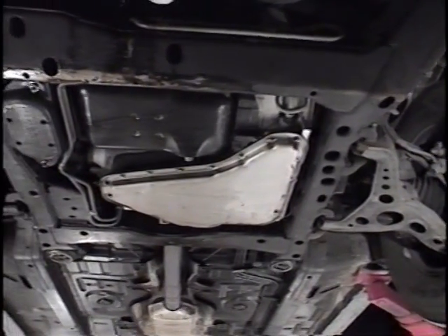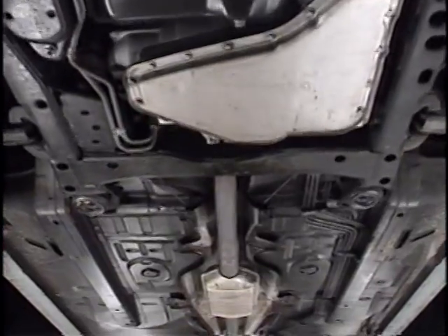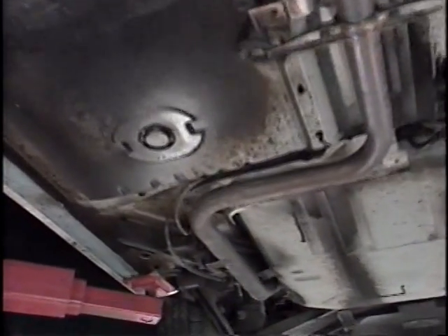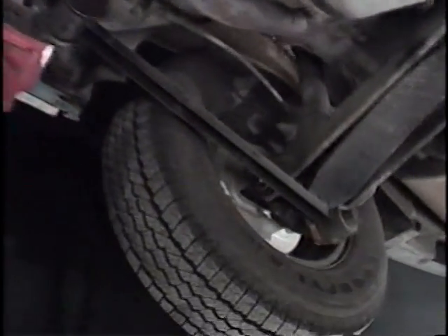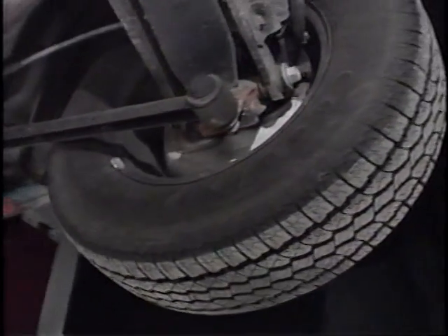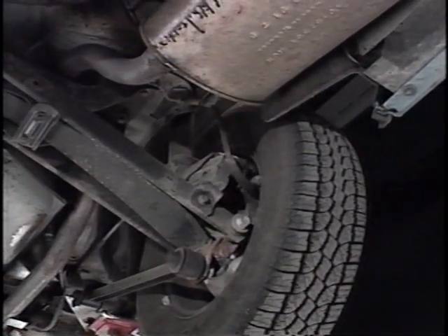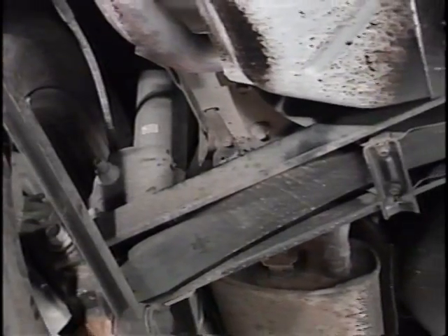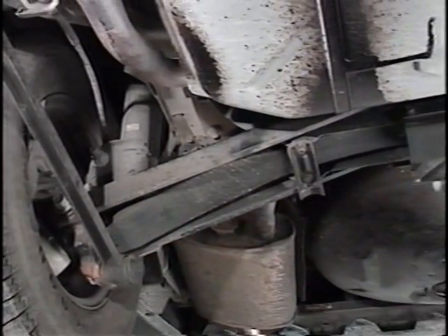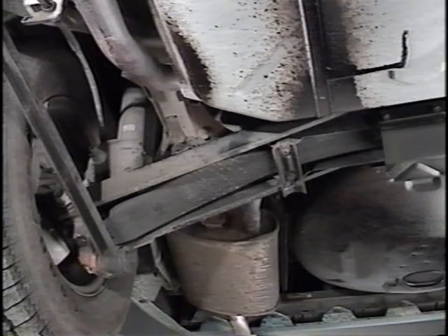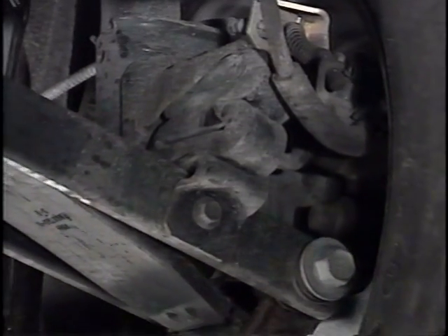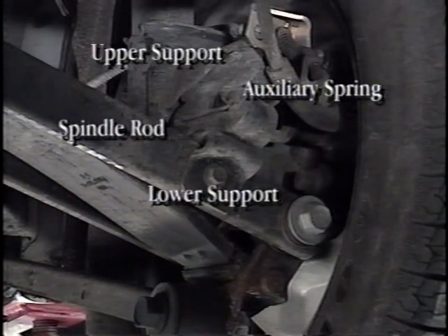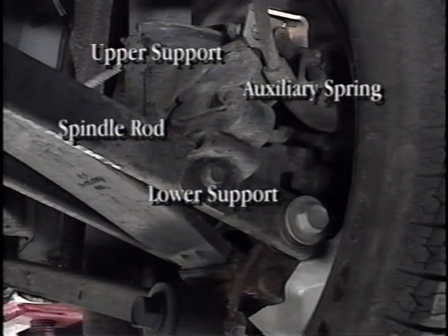There is a large variety of underbody noises, but the underbody noises most commonly identified on Regal models can be traced to a relatively small number of underbody and suspension components. The Regal has a unique, weight-saving, independent rear suspension system. The monoleaf transverse spring design eliminates the need for individual coil springs at the struts. On many models, additional cushioning is provided at each rear strut by a rubber auxiliary spring with two support brackets that bolt to the strut and the rear suspension spindle rod.